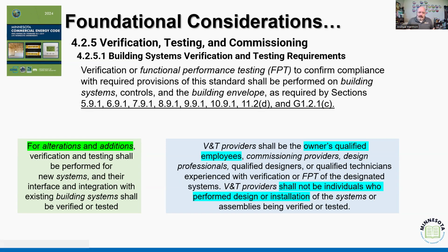What I'm not looking at in that 15 to 30-minute inspection process is, does it work right? I don't have my anemometer or my wind gauge out saying, okay, what was the expected CFMs of air movement at this duct? That's not what I'm there for. That's where again we come back to this concept of commissioning.